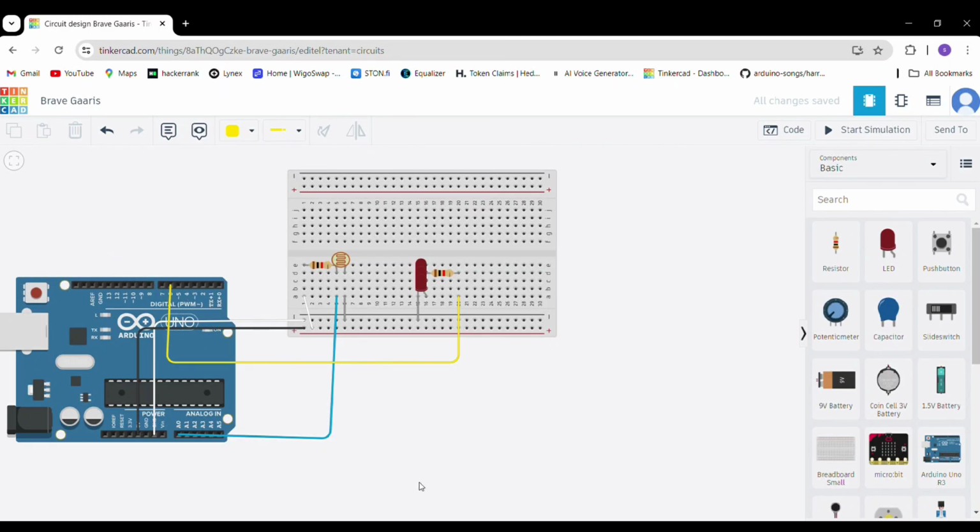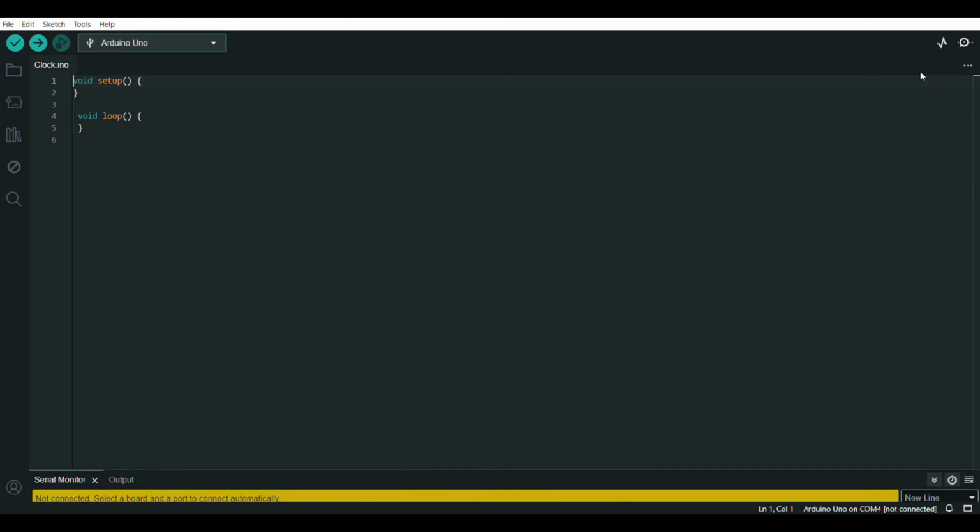Now let's write the code for this bad boy. Start by opening up your Arduino IDE and configuring your pins. Don't forget to include the stepper library since we are going to use it for this project. I will use 2048 steps to control my stepper motor rotations. Then I'll make an object of my stepper to be able to interact with it later.